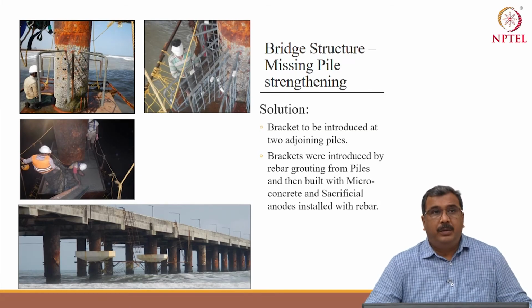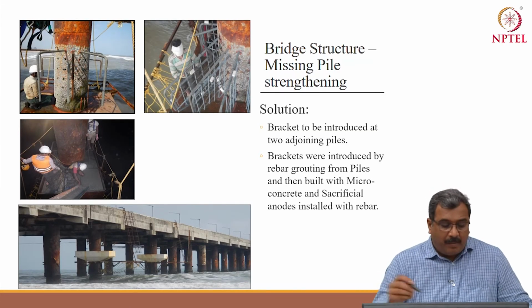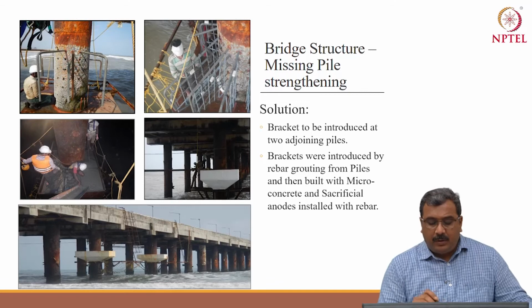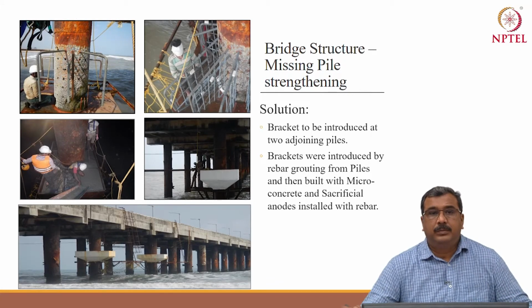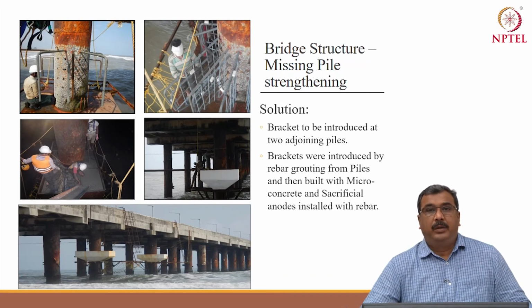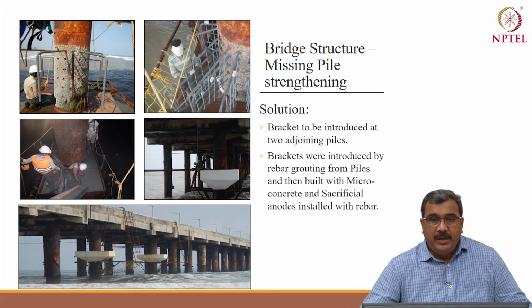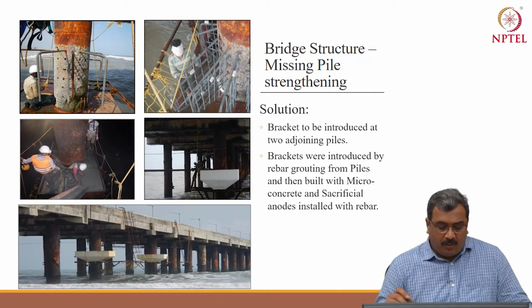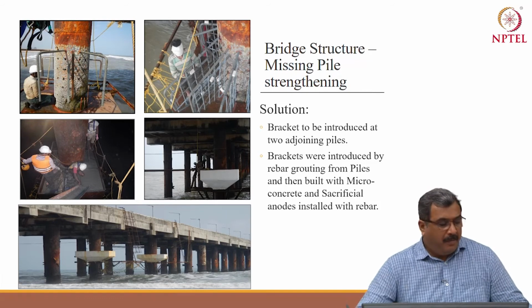shuttering has been provided, and micro concrete has been poured in the shuttering to form a bracket. These brackets have again been coated with a high performance anti-carbonation, anti-chloride ion diffusion, acrylic aliphatic coating. This is how two new brackets have been made.